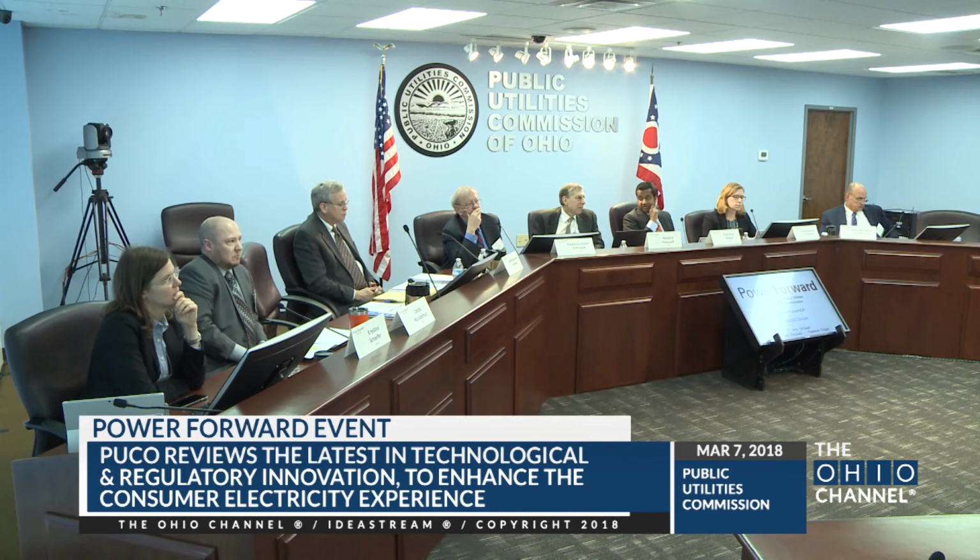Sure. So energy storage, once again, doesn't have a natural operating profile, so it all depends on who's controlling it and for what purpose. For example, if a customer or a utility is controlling it at the edge of the grid for some very local objective, that charge and discharge activity will have upstream impacts, and to the extent that it is the same need as upstream, that could be a benefit. So if you're doing peak load reduction from 2 to 4 p.m. on the distribution circuit, and that happens to also be the peak generation at the transmission level, you get 2 for 1. If the feeder level is from 10 p.m. to midnight, and the transmission level's from 2 to 4, now they're out of sync, and so you might have to do twice as many charges and discharges.